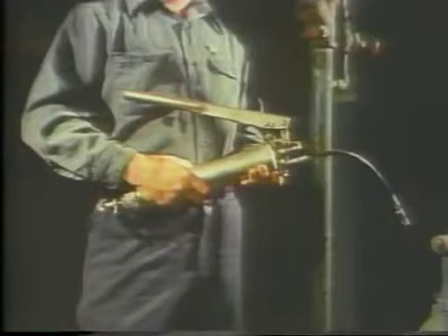Grease is usually applied to a bearing by using a grease gun. Grease is injected into the bearing through a grease fitting on the bearing housing. A grease fitting is a small rounded projection from the housing that has a hole through it. The fitting on the grease gun must match the fitting on the housing. To grease a bearing which has a fitting, it is often necessary to remove a drain plug from the housing before any grease is added.